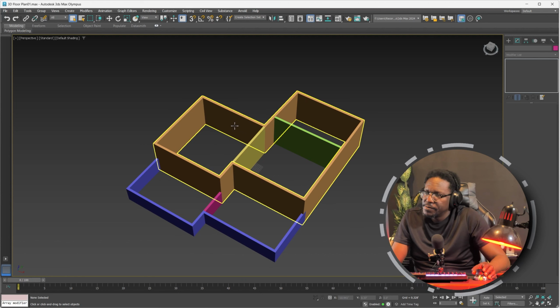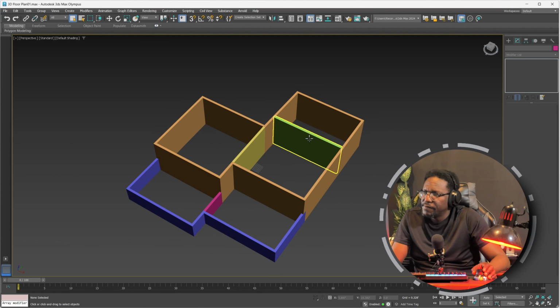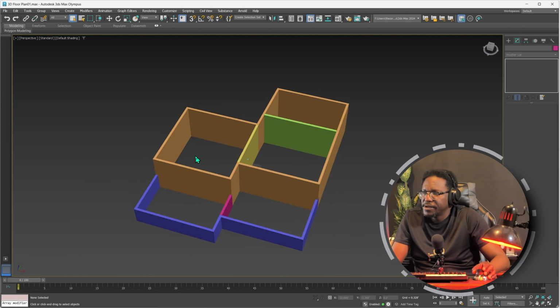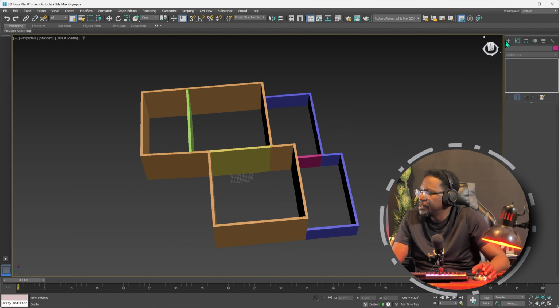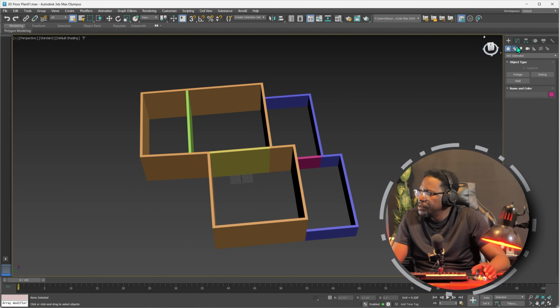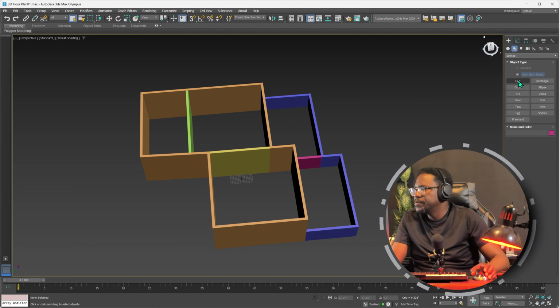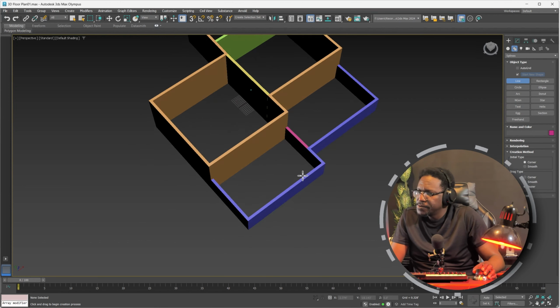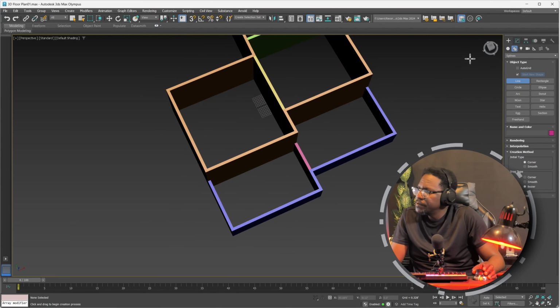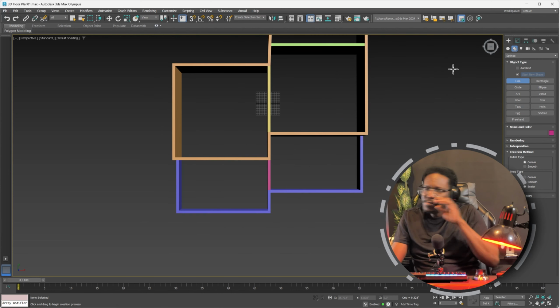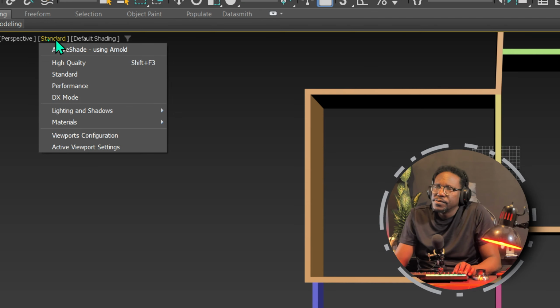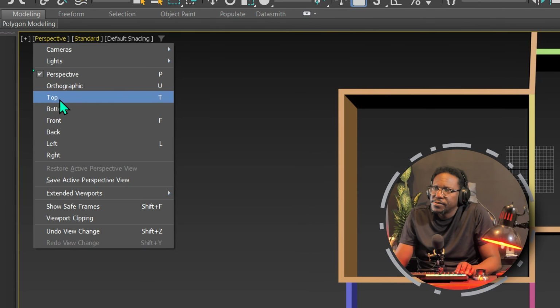So we're going to maybe want to see different floor patterns in these different areas. So hence we're going to need different solids. So we could use the create, then we go to shapes, and we could use our rectangle tool, or we could use our line tool. So let's use a line tool. And what we'll do, we'll go to a top view, and we will also go to our perspective and change this to a top view.